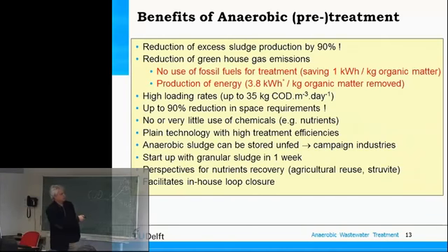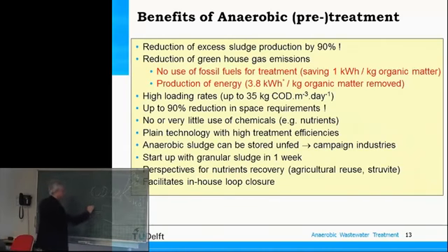Reactors using anaerobic technology are also very compact. You can load the systems with high loading rates, even up to 5 kilograms COD per cubic meter per day. And that is a loading. If you have a reactor system, you put some cubic meter per hour, and you have some kilogram of COD per cubic meter. Then it depends how much you can convert, given the amount of bacteria that you have, in terms of kilograms of COD per day, or kilograms of COD per cubic meter reactor volume per day. For aerobic technologies that can be up to 1, 2, 3 kilograms COD per cubic meter per day, and here we see indeed a factor of 10 higher. So reactors have a much smaller footprint, and are therefore very economic to put at the premises or adjacent to the industry.